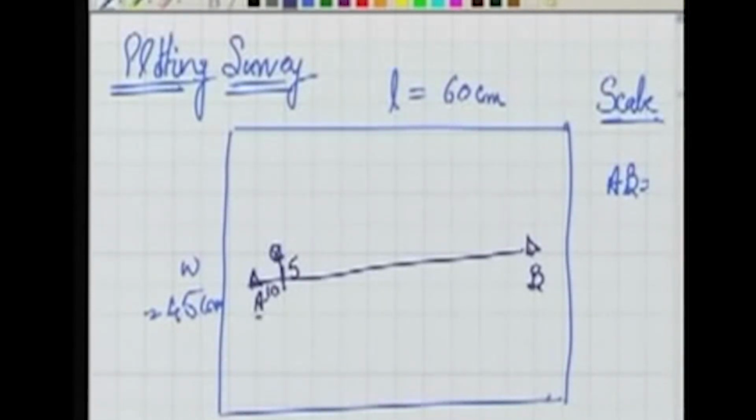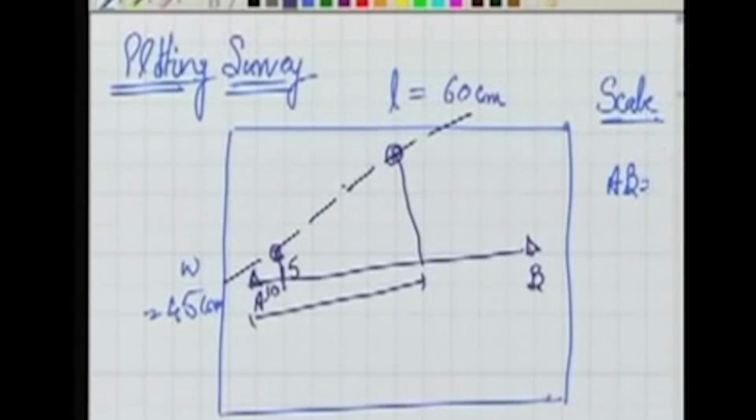Similarly, I can also plot another telephone pole, because I know its chainage, I know its offset, so another pole will be plotted. I know my telephone line is straight. I can join it. I know the telephone poles were at certain intervals, I can plot the rest of them.